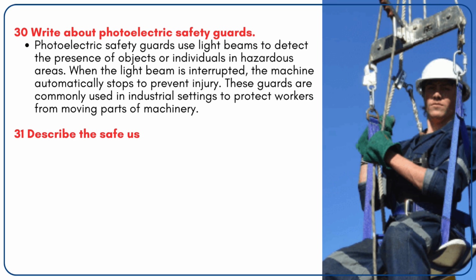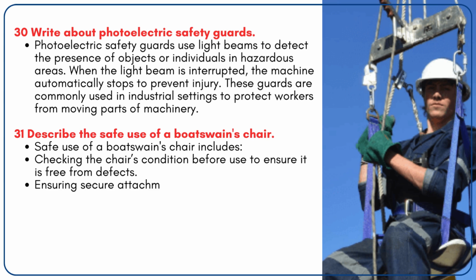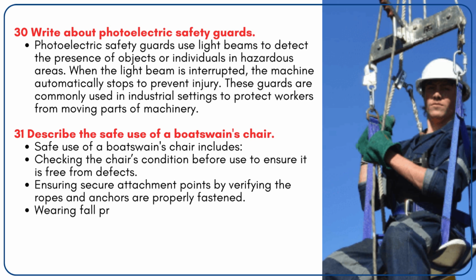31. Describe the safe use of a boatswain's chair. Safe use of a boatswain's chair includes checking the chair's condition before use to ensure it is free from defects. Ensuring secure attachment points by verifying the ropes and anchors are properly fastened.